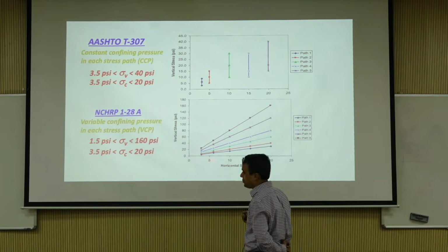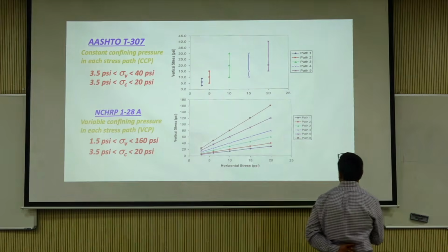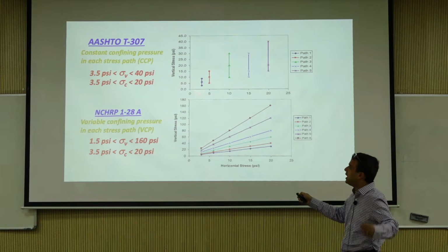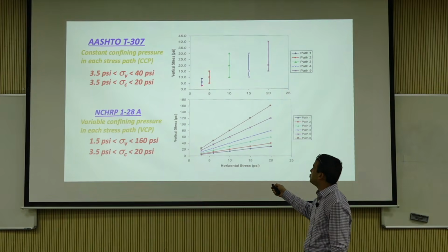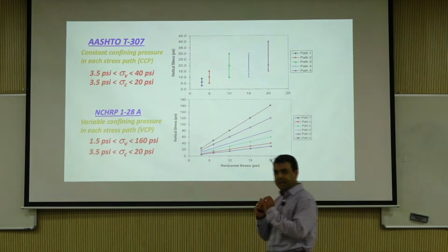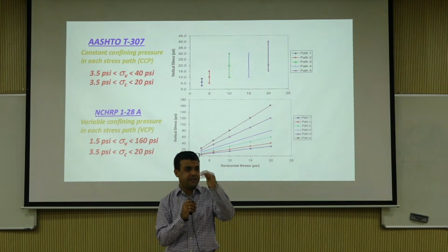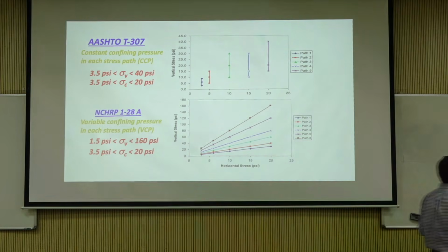So this is horizontal stress or confining pressure in this case, and this is in psi, folks, so just bear with me. This is basically 21 kPa. You can multiply by 7 as an approximation; it's 6.9 but close to 7. So 3 psi you apply, and then your deviator stress is 3, 6, 9. At the same confining pressure, you load it by 3. Let's go over the procedure first, because otherwise this is going to be difficult for you to understand.